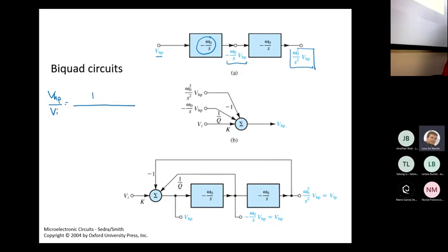We have a certain constant which multiplies S^2, because the high-pass filter is characterized by two zeros in the origin, and then we have the conventional denominator: S^2 plus S times omega0 over Q, plus omega0^2. Okay, we can now rearrange this formula. So let me jump back to the whiteboard.